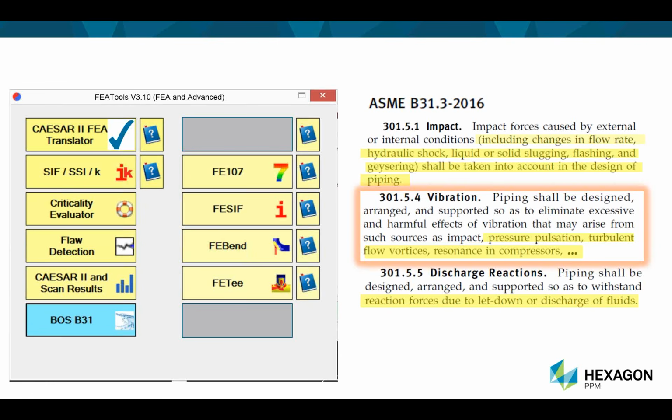And the idea is that when the user has a system with a significant tendency to shake, given these load types, and I think there are maybe 12 or so load types available, then it indicates that a more detailed analysis should be undertaken in BOSfluids transient, which you've just seen. And both Chris and Mark have mentioned a couple of times the coincidence of the acoustic frequencies with mechanical frequencies. This is a very simple tool that allows you to assess whether there is likely to be a problem or not.